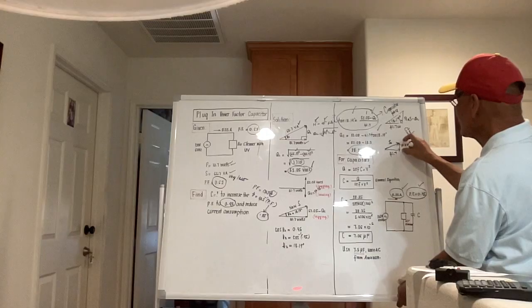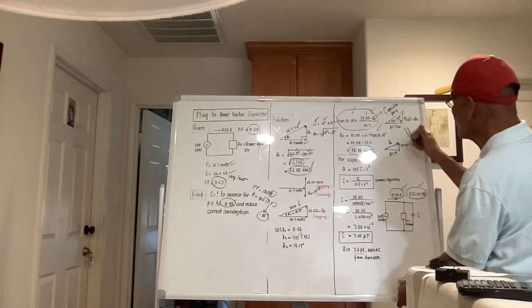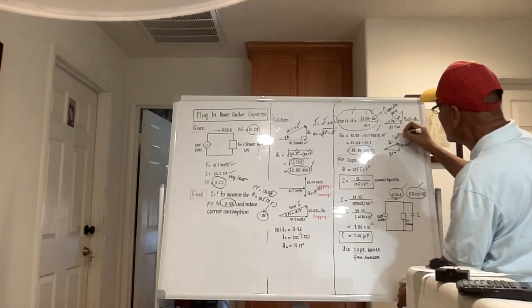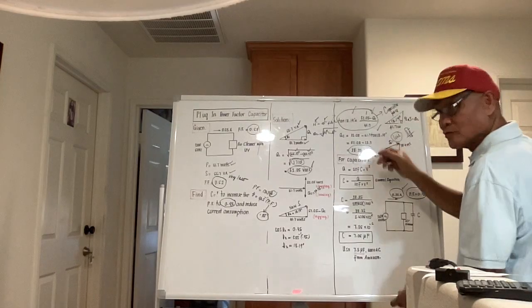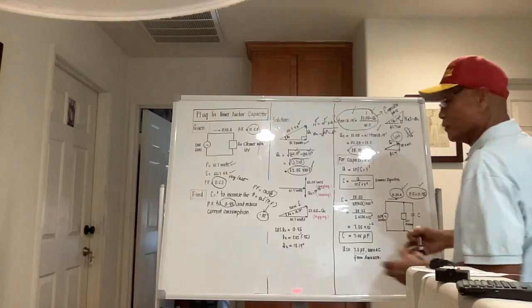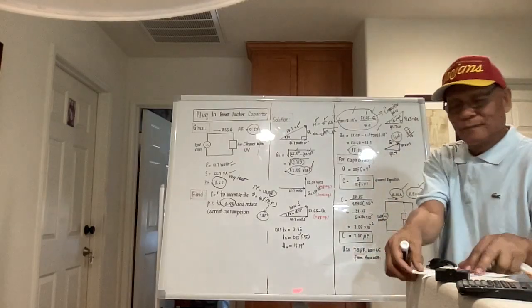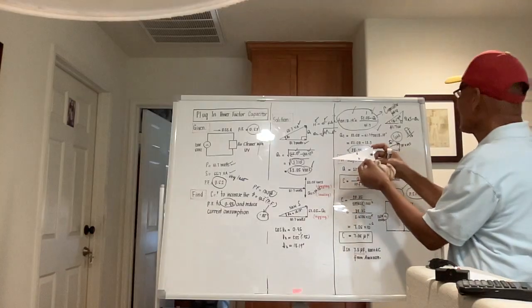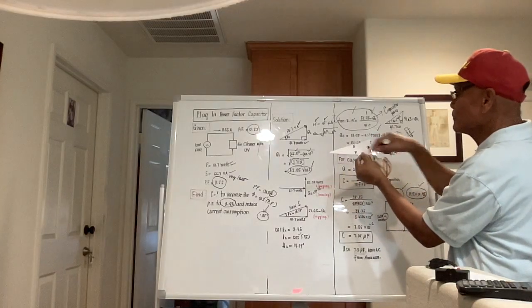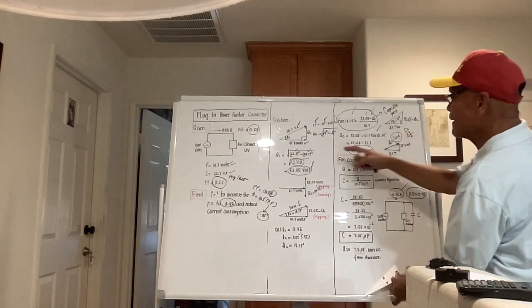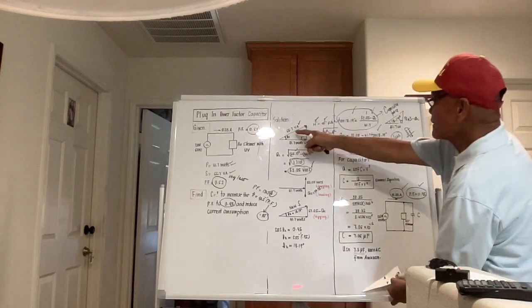So if we try to take the square of this plus the square of this, what will come out of this one will be less. It became smaller. That's the explanation of the power triangle. This became around 16 only, this is 41.7, so if we try to compute for this one, it will be less than the original 66.7.